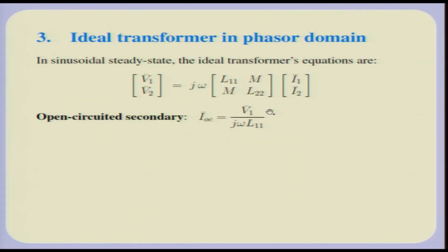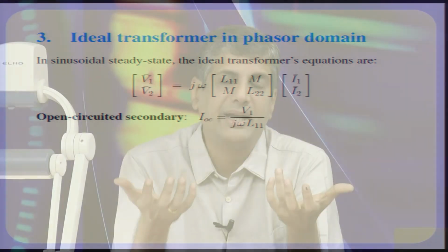But another important point which you should remember is that you can have more than 2 coils, you can have 3 coils, and they could all be mutually coupled. In that case, of course, you would have a 3 by 3 matrix for the three coils, and in fact that would also be a symmetric matrix. So, mutual inductances between the coils taking 2 at a time would come out to be equal. So, the mutual coupling between 2 coils is always equal. Okay. So, you always have a symmetric matrix.